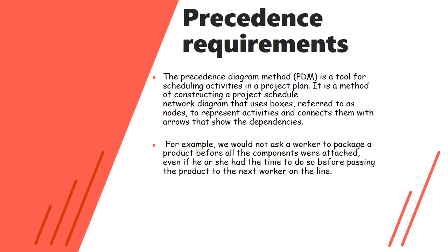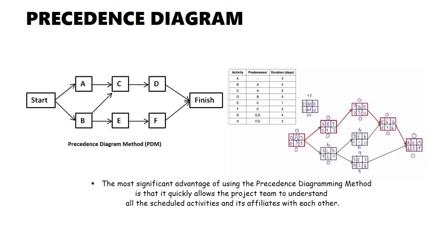To facilitate line balancing, precedence requirements are often expressed in the form of a precedence diagram that I will show to you later. The precedence diagram is a network with work elements represented by circles or nodes, and precedence relationships represented by directed line segments connecting the nodes. So, here is the precedence diagram method, or we call PDM, a diagram that describes the order in which work elements should be performed. It shows that some jobs cannot be performed unless their precedents are completed. The layout of workstations along the assembly line depends on the precedence diagram.